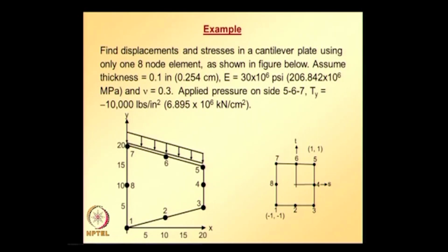So, in total, you can guess 9 integration points are there, and I guess you know how to obtain the corresponding weights and coordinates for all these points. So, now the calculations will be illustrated for one integration point. A similar process can be repeated for the other integration points, and the contributions from all integration points can be added up to get the final element stiffness matrix.